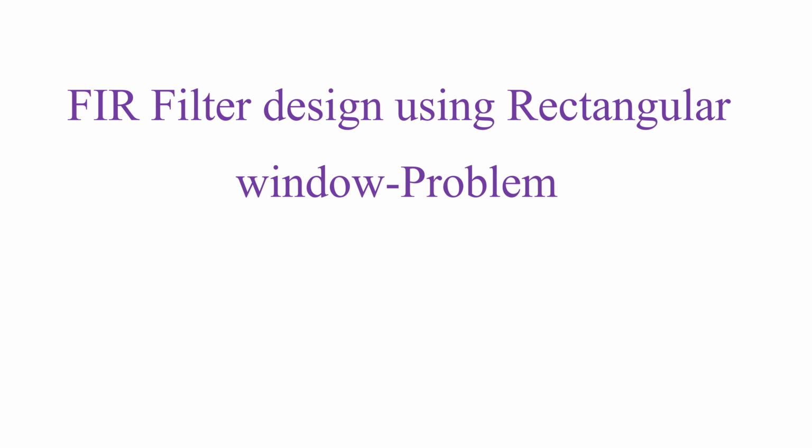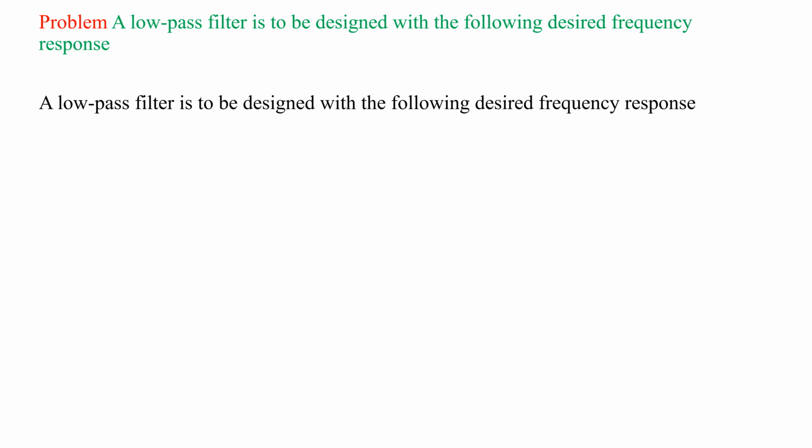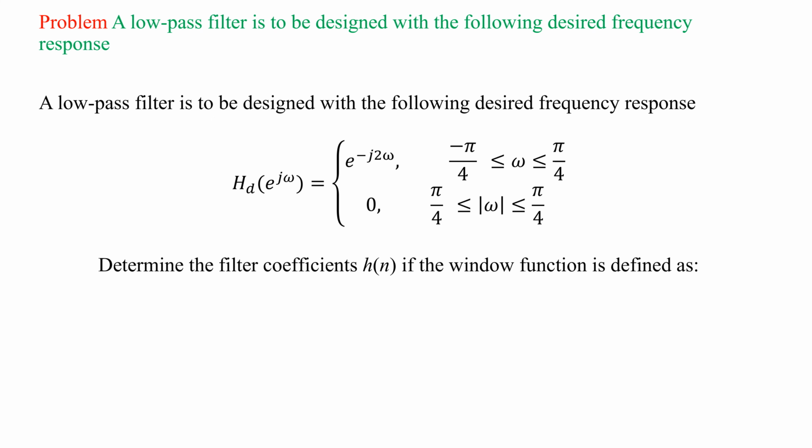We are going to see FIR filter design using rectangular window. Here a problem is given. In this problem, we have to find the frequency response and the filter is the low pass filter. The frequency response is given, capital HD of e power j omega, and it is the desired frequency response. We have to find the filter coefficients h of n.